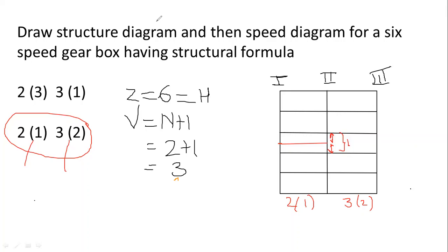So I already understood where my end points are going to lie. It is going to lie here, and I have to draw two lines which are going to touch there. So I'll start from here. This is my first line and this is my second line. So guys, you can see here I have completed this portion which says 2, 1, meaning two lines with the gap of 1. I'll rub these unnecessary things. Now I'll rub this line also because it was just a center line. So two lines with the gap of 1. You can see here this gap is the total gap of 1, half above and half below from the center line.